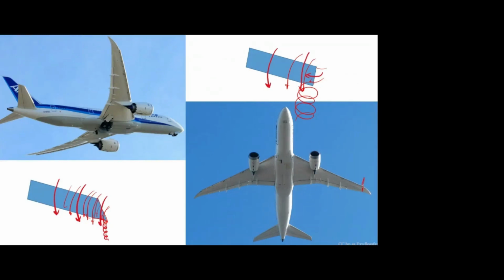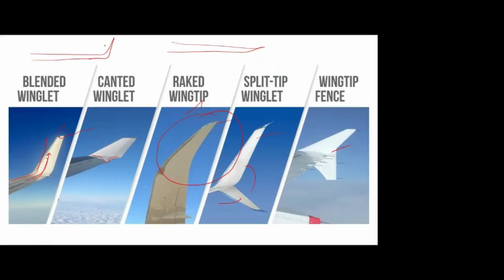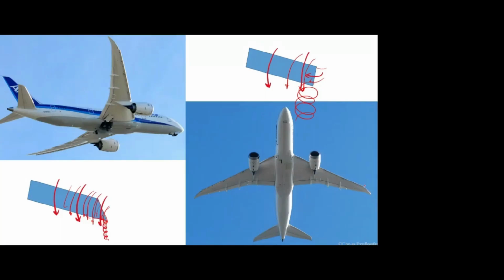Conventional means there will be an additional vertical plate here, right? So in the conventional one, only this area produces effective lift. This vertical portion will not contribute any lift. It may produce some side force, that's it. But if you go for the raked winglet, this extension portion also effectively produces lift. So it is effectively reducing the wingtip vortices. It also produces additional lift because it is flat, aligned in the same direction as the wing. So this portion additionally produces lift. Is that clear?